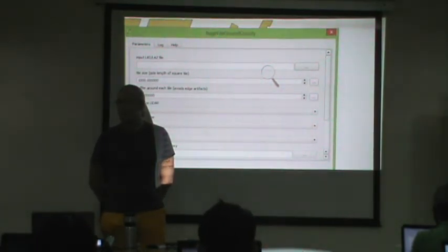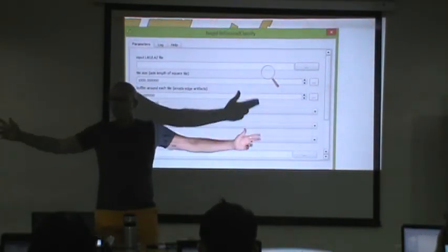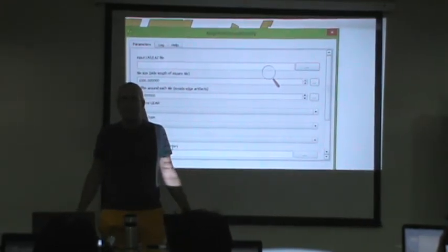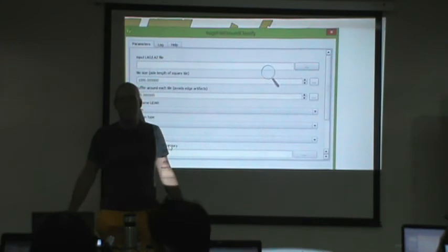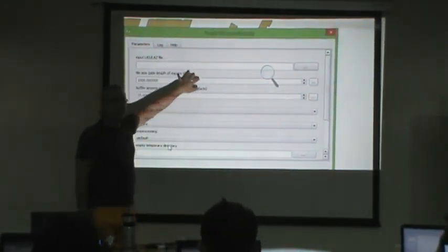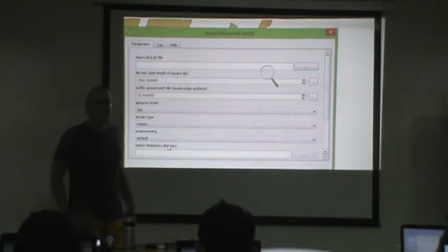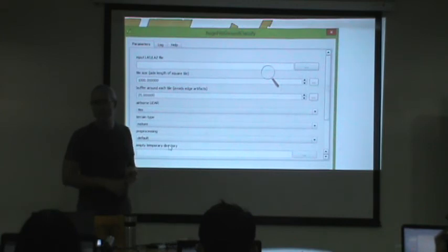If the file is bigger, it will run out of memory. But what if you have a flight strip, a long flight strip, and for some reason you need to classify that whole strip, like it is, and it's 250 million points. What do you do? You need a ground classified pipeline. I have a batch script for that in the batch script folder. I have an ArcGIS pipeline for that in the ArcGIS model, and I have a QGIS model for that.